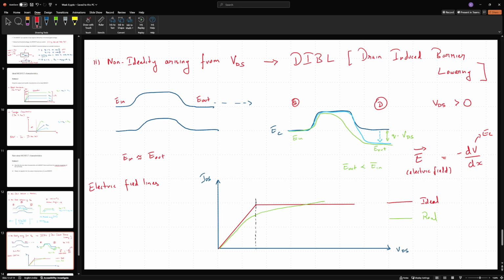So remember, the curvature of the electric field lines gives me the magnitude of the electric field. Okay. So like if there are two very high charges, the electric field will curve very strongly next to them. Okay. In the channel. So if I have a long channel, and this is Vs and Vd, then Vd minus Vs is going to give me electric field lines that will kind of move like this. It'll be like this and like this. And eventually there is going to be a field line long enough to connect these two, which implies it will start accelerating electrons across the channel. Okay, in fact, these electric field lines have to be symmetric. I'm really sorry that I could not make them symmetric.